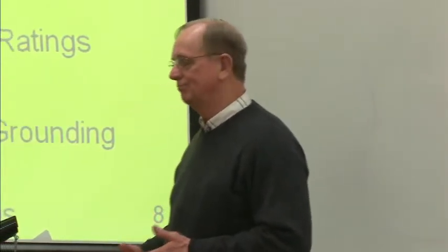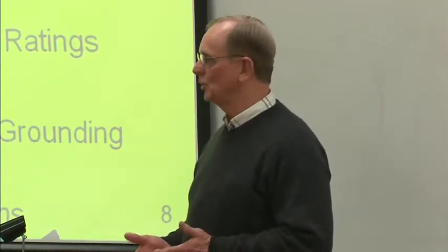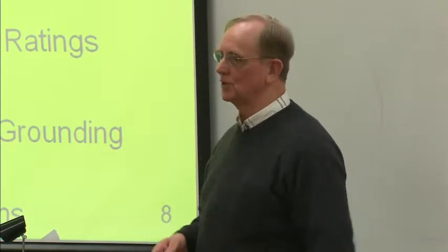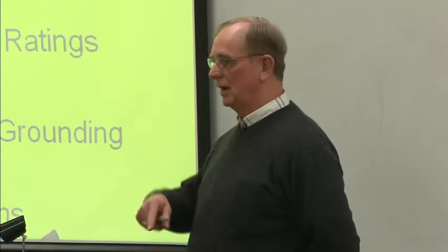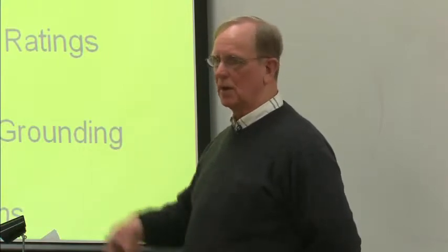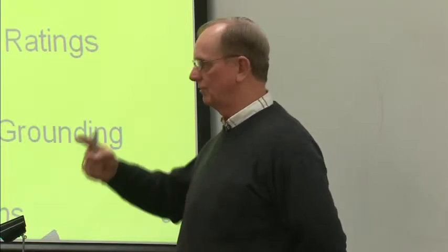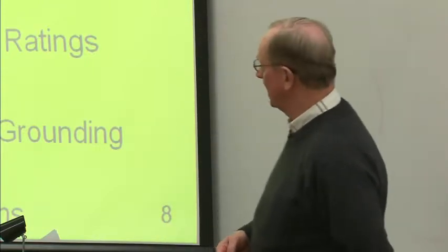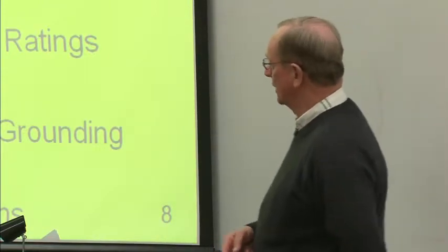When those devices first came out, they were set at 10 milliamps. Discovered not too long after that that that wasn't adequate, so they lowered the standard to 5 milliamps to be able to cut off the current. That's 5 thousandths of an amp. And it's not the amount of current going through the circuit. You may have 20 amps going through the circuit, but it's that amount that flows outside through the resistance in a body then that the device senses. All of those things have to be taken into account to end up with the right kind of selective coordination.